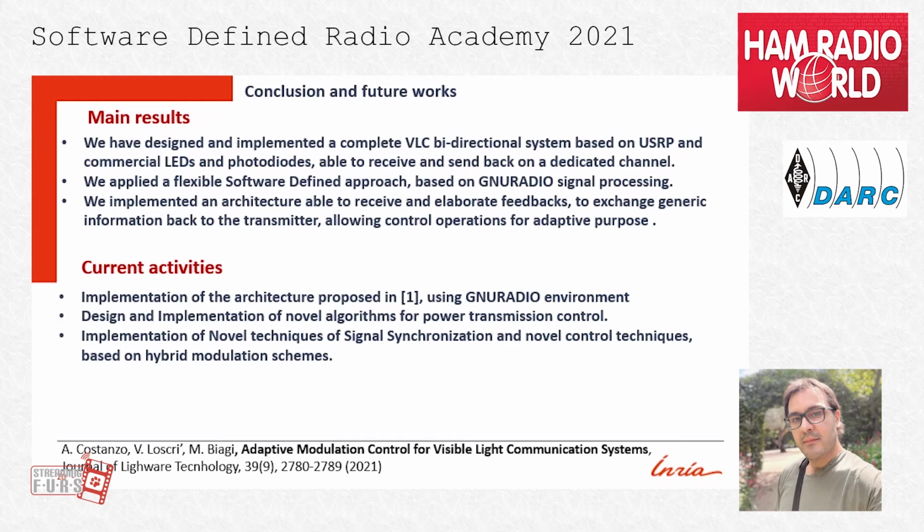And we are designing and implementing other algorithms for power transmission control, like the one that I showed you in the last slide, but also something more sophisticated. And we want to implement some other novel techniques of signal synchronization in order to improve our system, and also other modulation schemes, for example, mixing PIM and PPM in the same system in order to increase the performance in terms of rate, but also in terms of noise robustness.